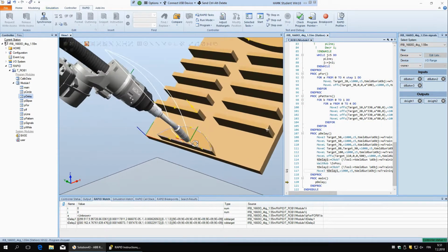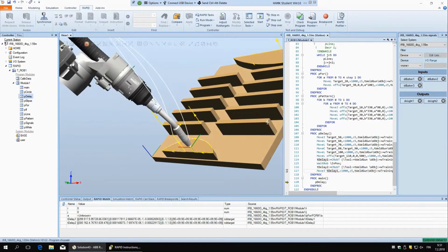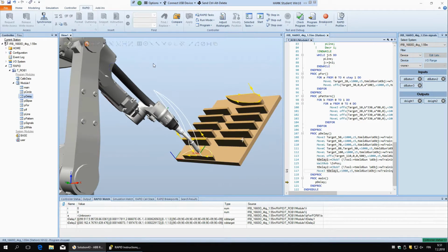So you can see the signal went forward already here. So if you would have some kind of output here saying, okay, I'm ready, and then something else will start moving, there is a good chance of something, like I said before, crashing into each other. So this is really important that you keep this in mind. This WaitRob in position is a really useful command that I think you will need a lot of times.